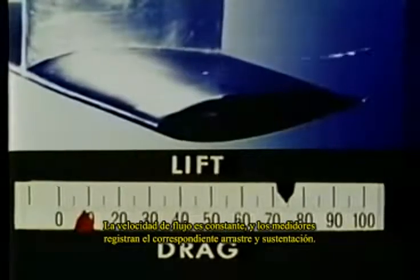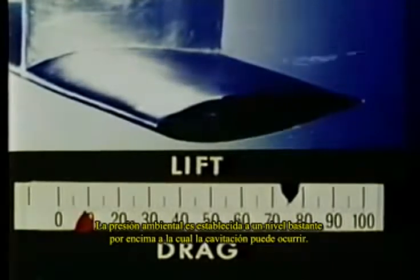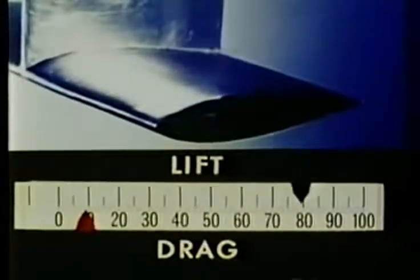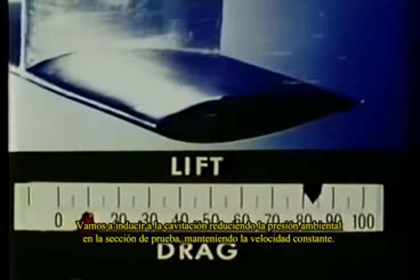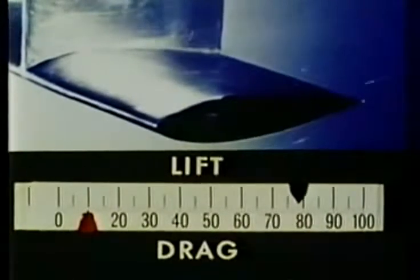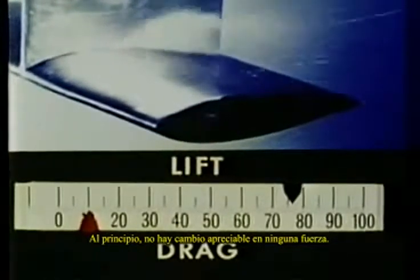The flow speed is constant, and the gauges register the corresponding lift and drag. The ambient pressure is set at a level well above that at which cavitation can occur. We are going to induce cavitation by decreasing the ambient pressure in the test section, keeping the speed constant. At first, there is no appreciable change in either force.